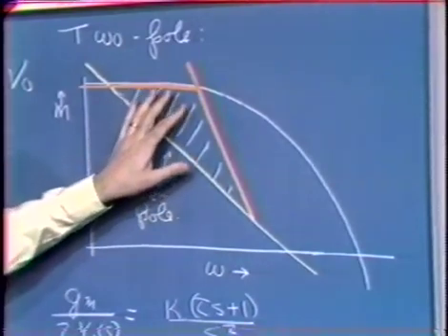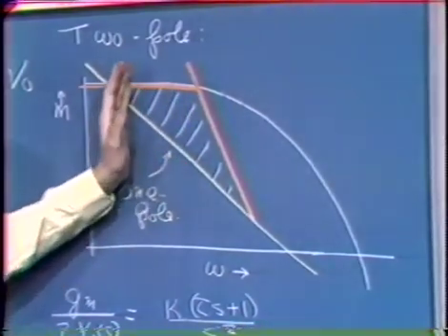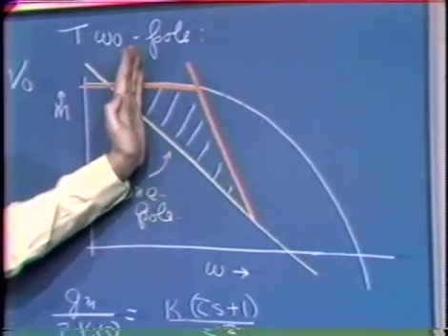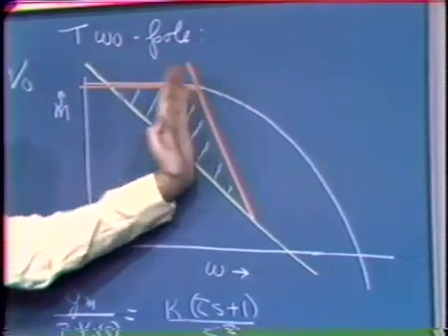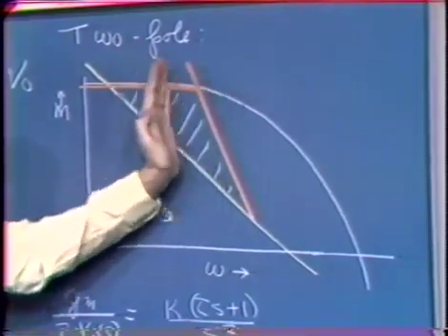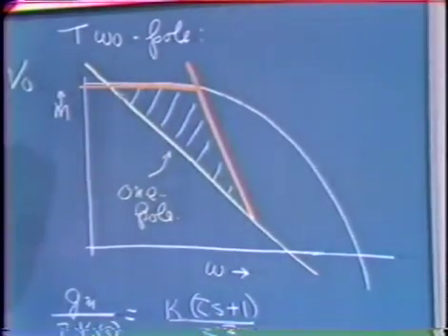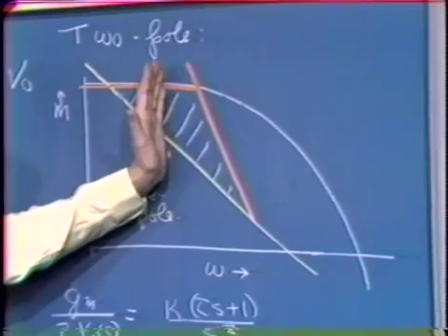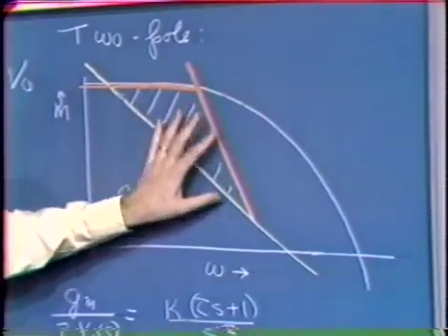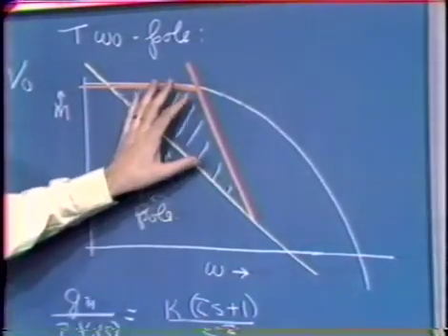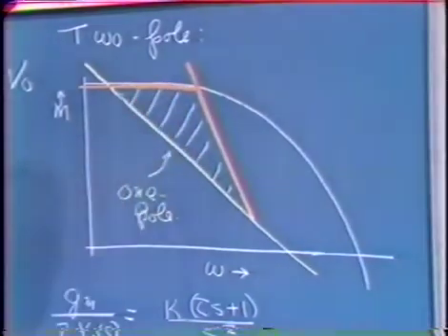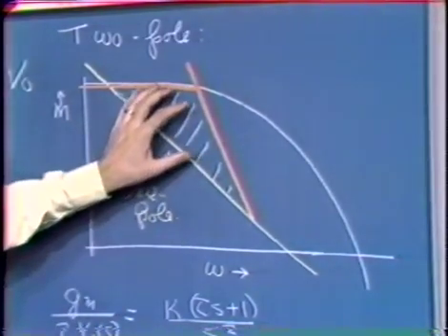We'd anticipate improved desensitivity for any signal where most of the signal energy was concentrated in this region. The triangle wave that we've chosen happens to be one like that, where the 5 kilohertz fundamental and most of the appropriate harmonics lie in this region. We get greatly improved desensitivity, a much smaller error signal in the system.